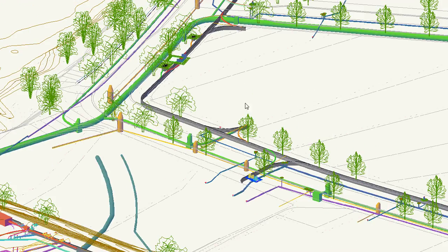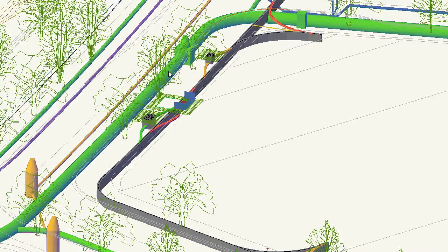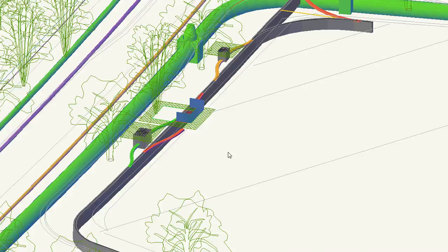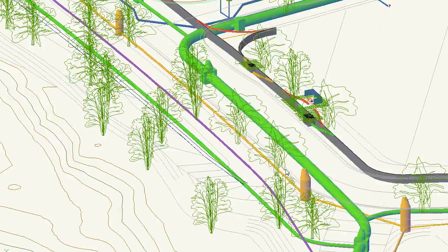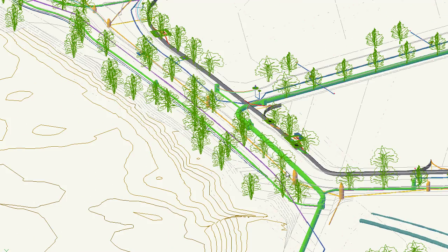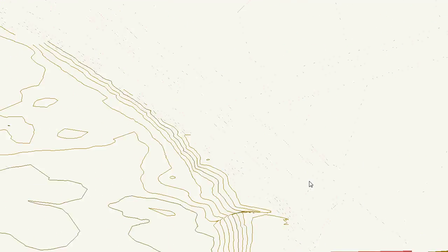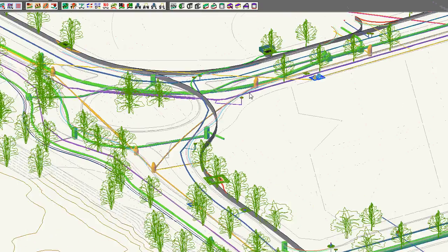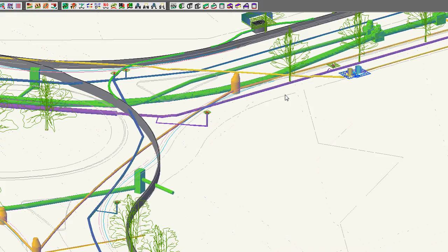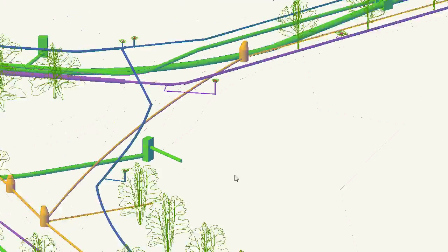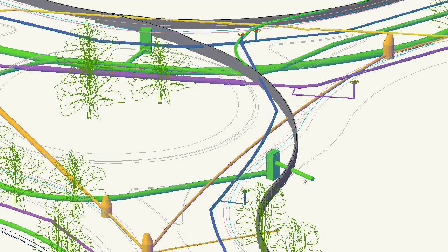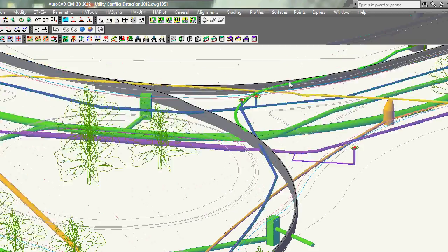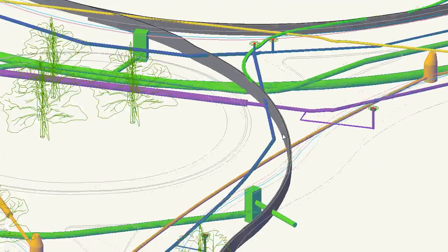We haven't actually modeled how the conclusion of that is going to be, which goes under what and what moves around, but usually it's the dries moving around because the wets have already been through submittal, so you'll see a lot of dries crossing wets or storm drain in this sense, but you won't see any of the wets crossing anything else, because that's been all coordinated and plan and profile done.